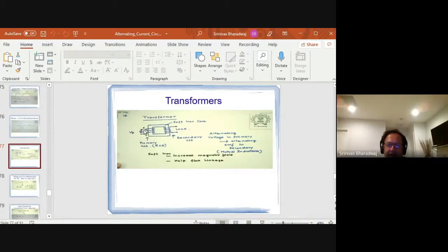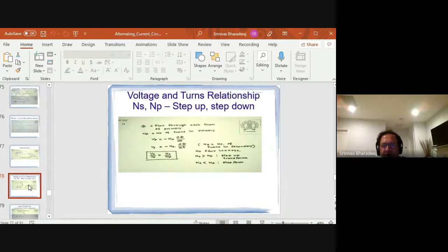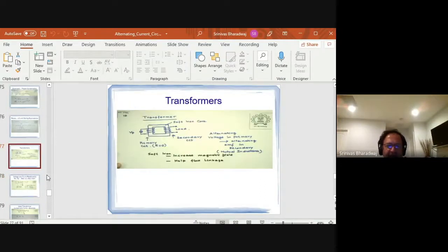They supply a voltage on this side. When you wind it and supply a voltage on this side, there will be an induced current in the other side. Okay, that's how transformers work. Now, based on the number of coils on this side versus that side, N1 to N2, you will either have a step up or a step down. Which side is bigger, has more coils, will determine whether it's a step up or a step down. So that is the number of turns in the primary. When they say number of turns, they mean how many coils in this side versus that side.